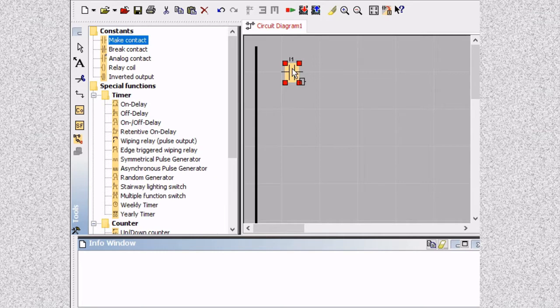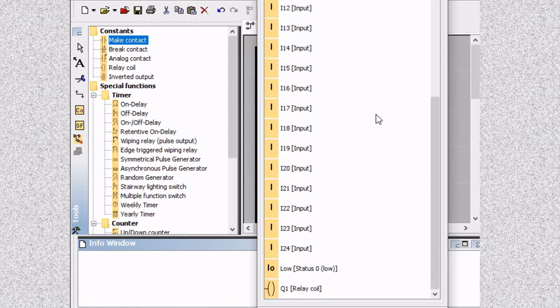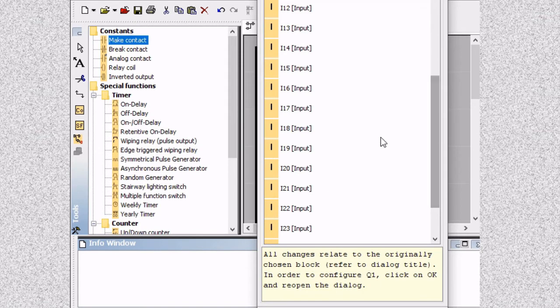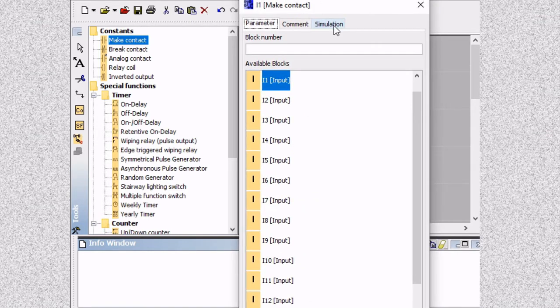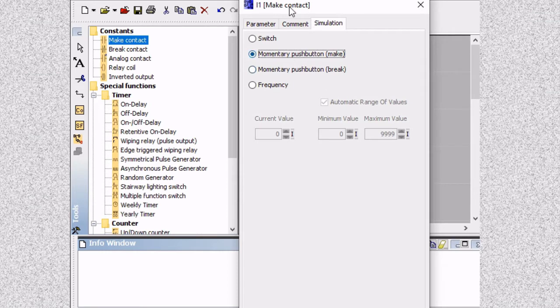where you've got an input that will be my start button that connects to my output relay, and then I include another input which I then identify as my relay coil. That then gets placed in parallel with my start button. The start button, I am going to make a push to make button.